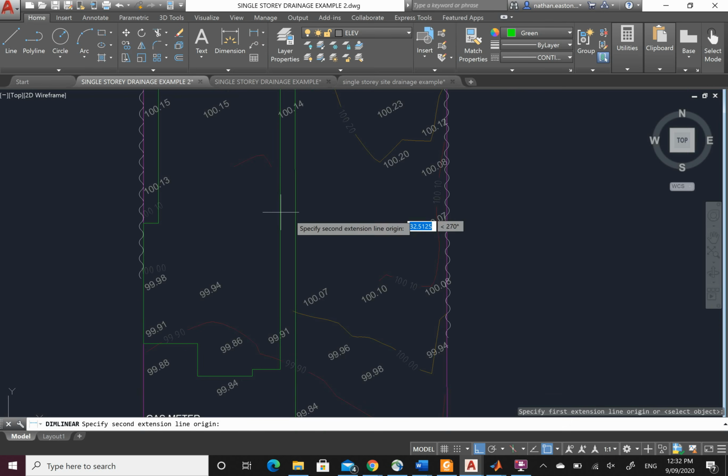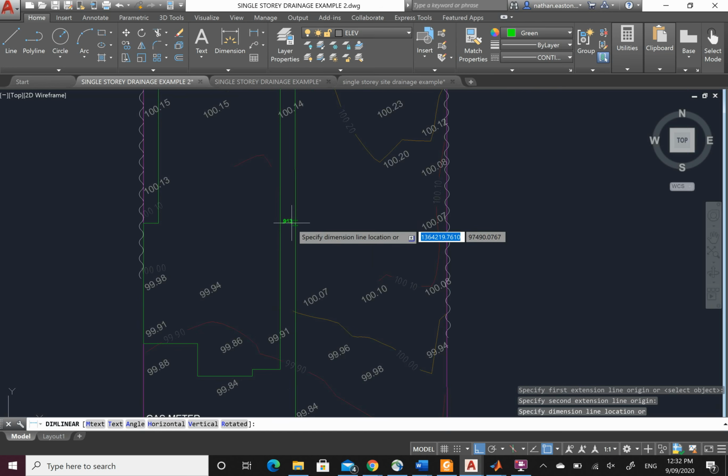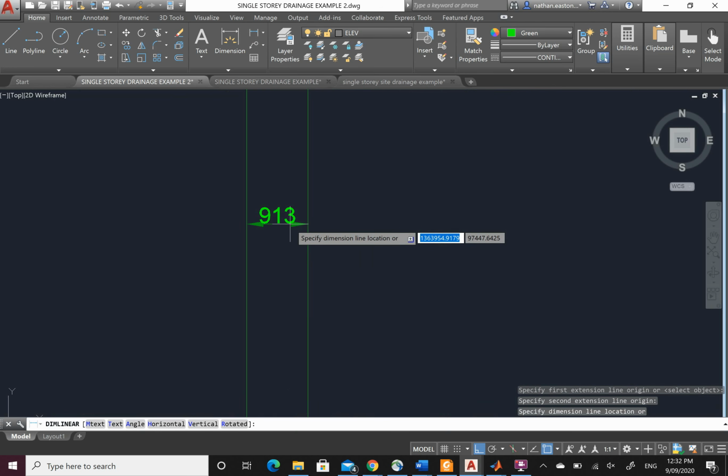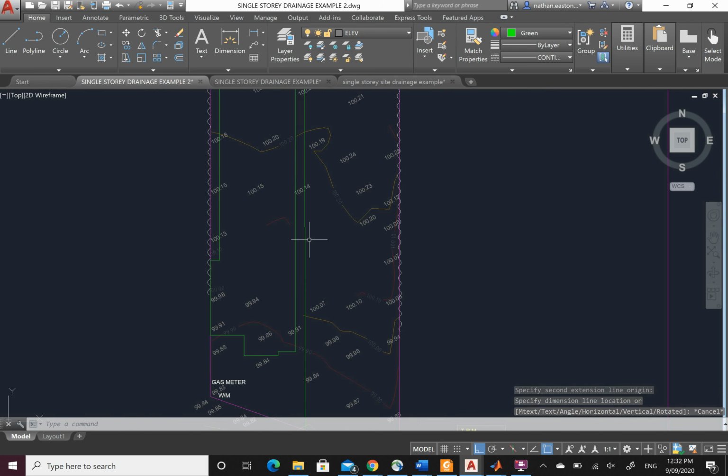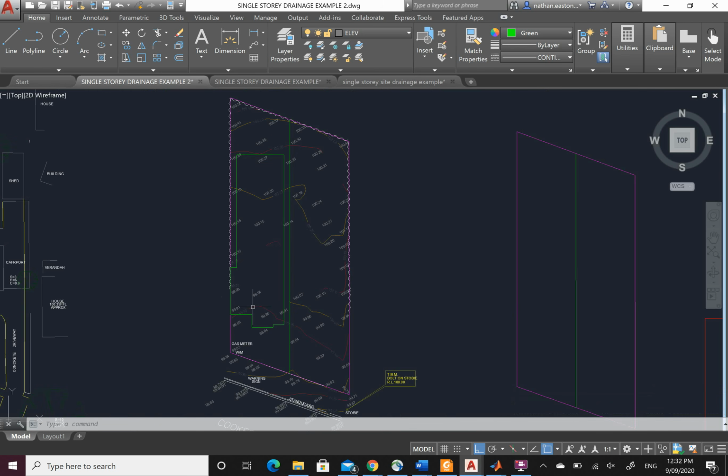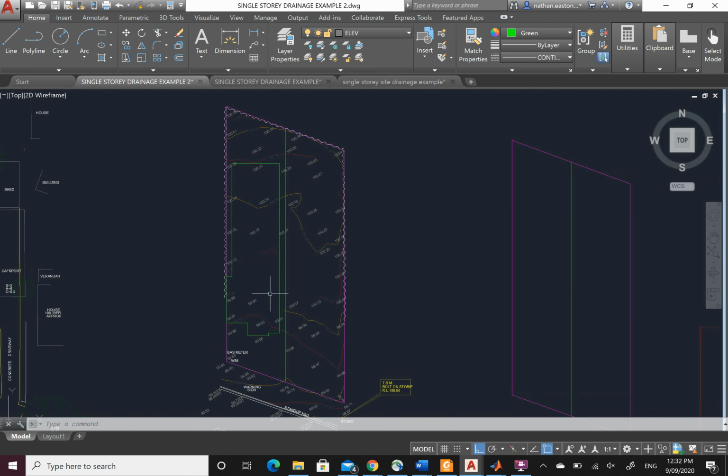Let's check here. On the side, we have to have at least a 900mm boundary, which we do, which is nice. So we have to have an access path to the back of the house, and we have to have a concrete perimeter around it as per the National Construction Code. You will learn more about this in geotech and your design projects, but I'll just download a bit of information to you now. The next thing that I need on here is my roof outline.